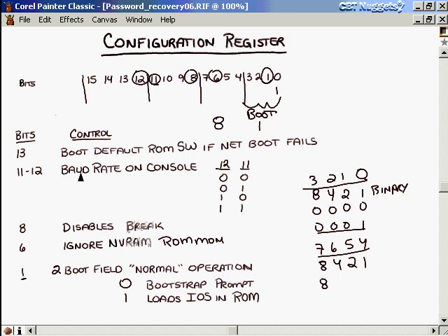If you'll remember, we opted in our settings for 9600 when connecting to our router as a baud rate. That's the value if 12 and 11 are both zeros. Okay, so that's 9600. In fact, let me finish out this table for you. 0 and 1 together, that's going to be 4800. 1 and a 0 is going to be 1200. And then 1 and 1 together results in 2400. This is the speed, the baud rate at which we make our connections.